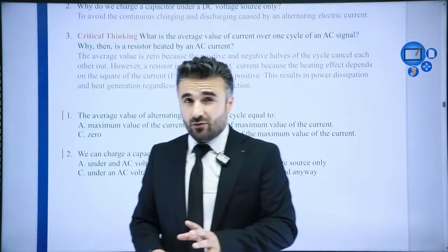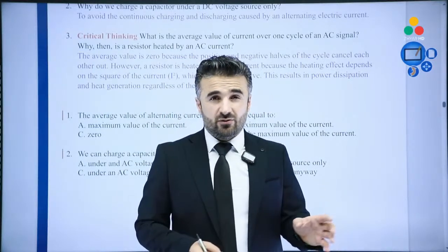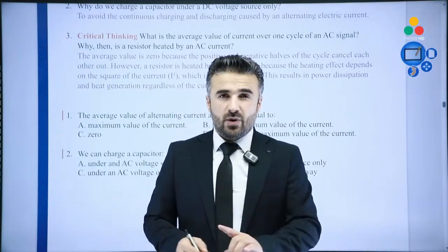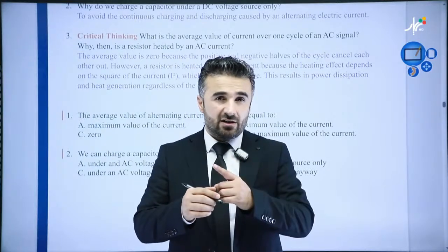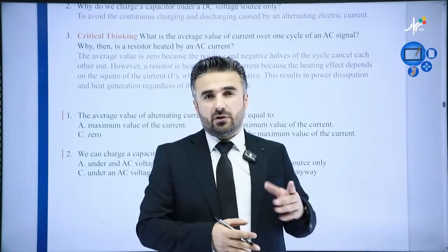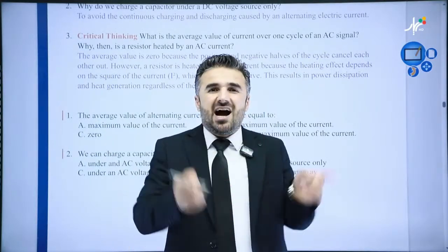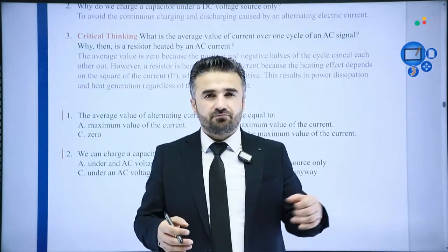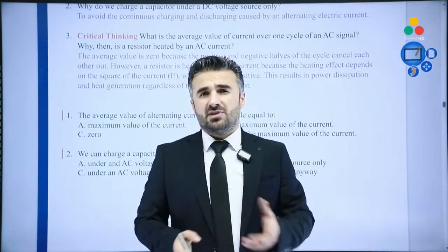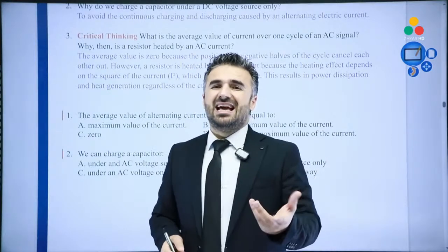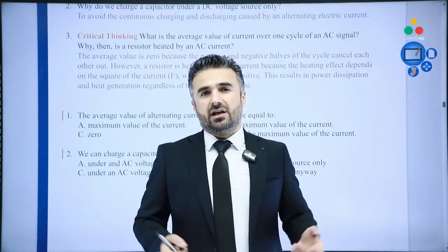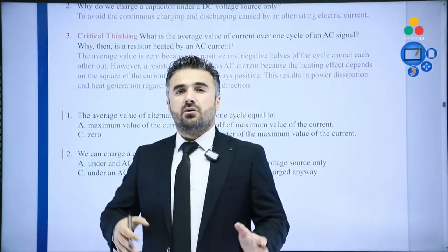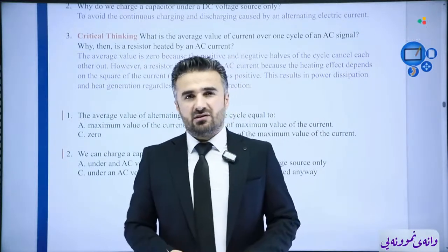Okay, the answer to that, whether current is positive or negative, is that we use the equation for power, which is basically I squared times the resistance. That is the power loss equation, correct? So when we say I squared, the current squared, whether it is positive or negative, it still comes out positive. Let's say -5. -5 squared, you get positive 25, correct? So as a result, you always get a positive value.